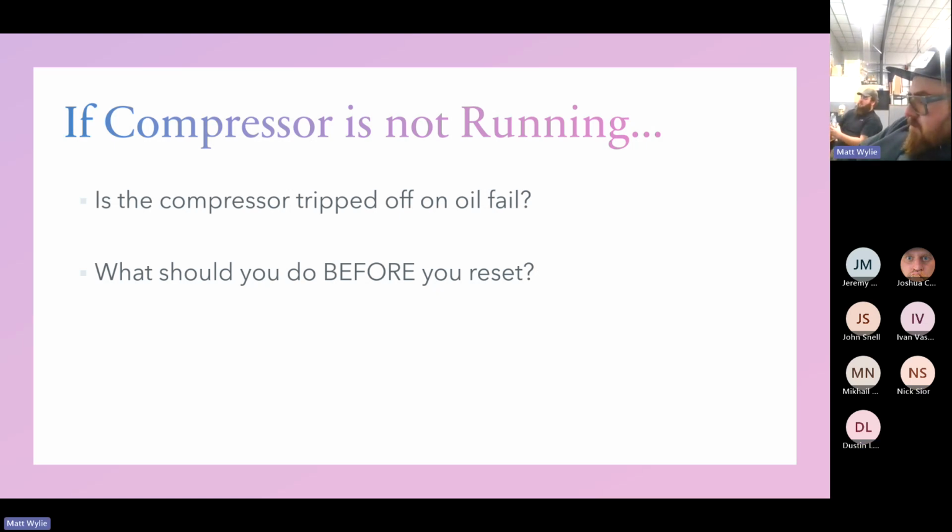You don't just dump oil in the system though, because you could end up putting tons of oil in the system that you don't need. Low pressure, like I've seen some where it's just cut out and refrigerant isn't coming back because it's blocked from getting back. So just blockages in the oil refrigerant line, separator or the oil float. Yeah, you could have that. An oil filter could be restricted, right?